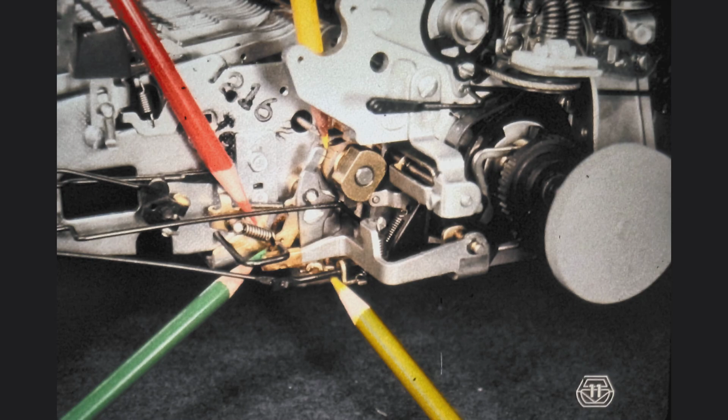The low-velocity mechanism restoring cam is mounted on the filter shaft, so it rotates whenever the cycle clutch or print clutch operates. When the machine is at rest, the cam follower is held rotated counterclockwise by the restoring cam. During printing, the cam follower cannot follow the contour of the cam unless the low-velocity selector latch is first rotated out of the way. Most of the time, the low-velocity selector latch prevents the low-velocity actuator from rotating.